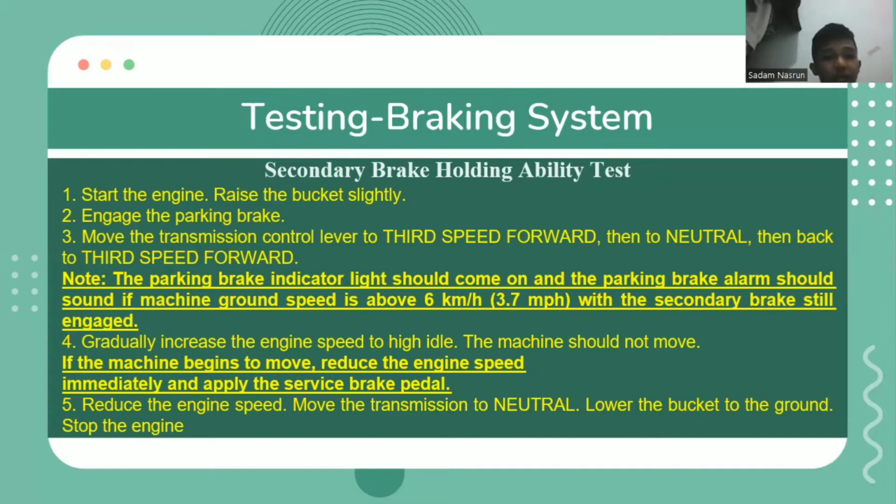If the machine begins to move, reduce the engine speed immediately and apply the service brake pedal. And number five, reduce the engine speed, move the transmission to neutral, lower the bucket to the ground, stop the engine.